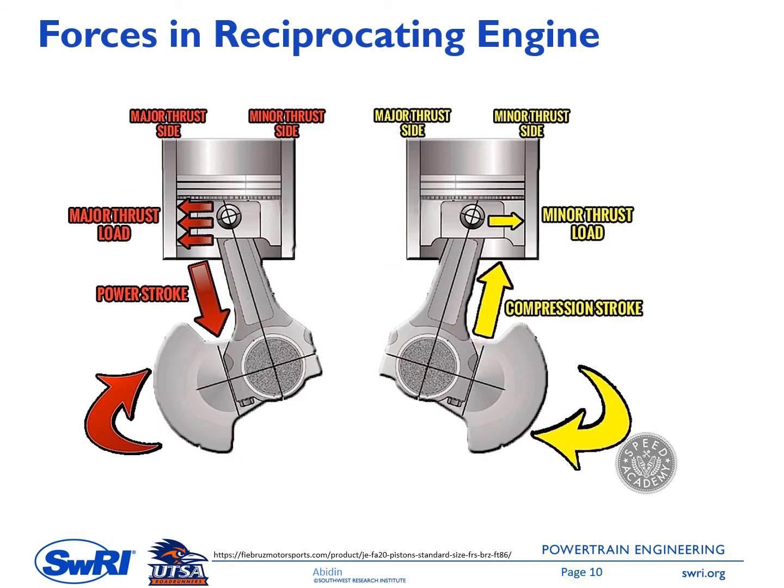This figure is showing the schematic for the impact of the force to the cylinder blocks. In this case, we assume that the crank rotation is in the clockwise direction. The first figure on the left side is when we have a combustion. It generates a high gas pressure, and it pushes the piston down toward bottom center.